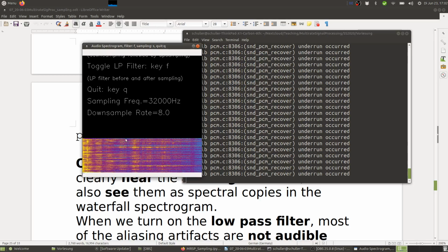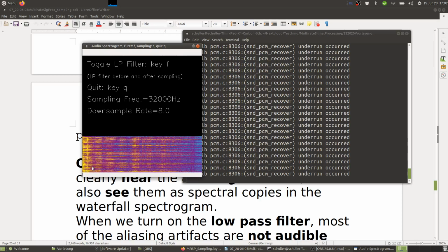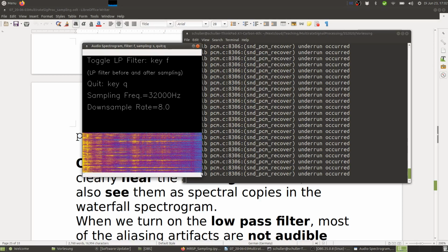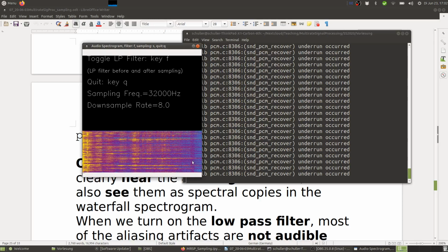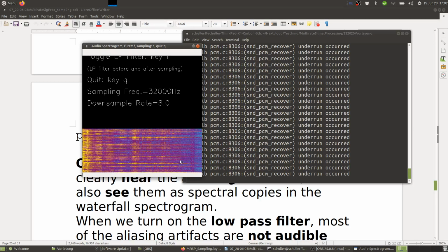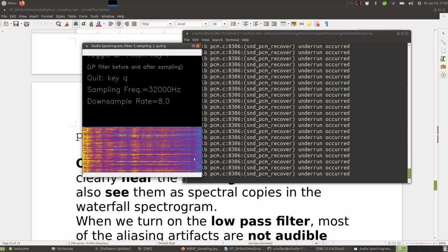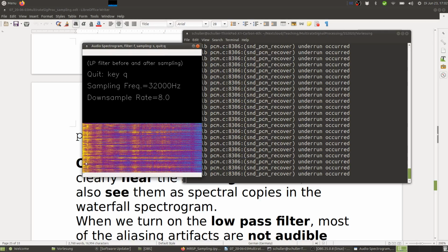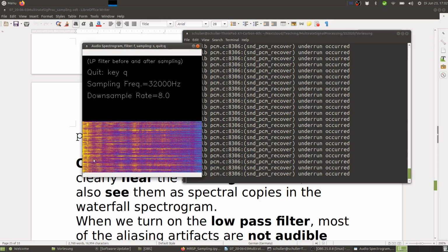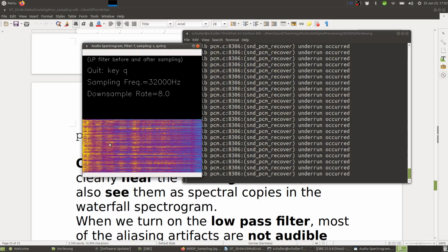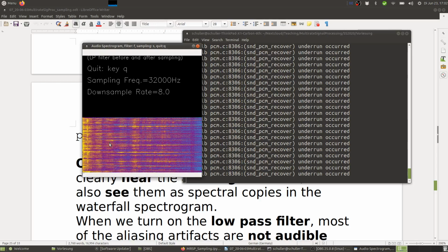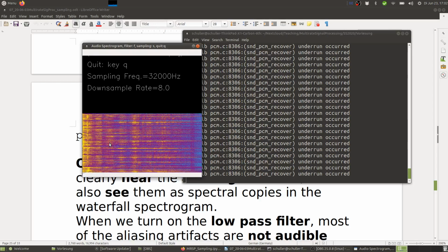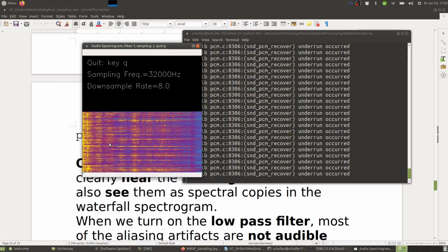So right now you can already see the spectrogram happening. Left is frequency 0, and to the right we have Nyquist. You can see the high frequencies are bluish, so there's not much. Most energy is in the middle, and particularly in the low frequencies. So you hear my voice directly, and also after processing, that's why you have this echoey effect.